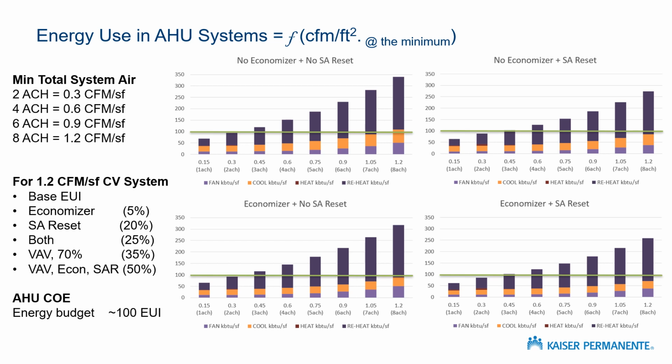The amount of air that we're using at that condition is the minimum air of the system, and that drives the energy signature for the hospital. And so our energy goal for hospitals in general is 125 EUI points. So if you assume that roughly 10 EUI points of that is lights and another 10 EUI points of that is plug loads, then we want to get right around 100 EUI of our HVAC systems. In order to get there, you've got to be somewhere in the neighborhood of 0.3, 0.4, maybe maximum 0.45 CFM per square foot at the neutral condition.